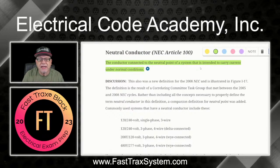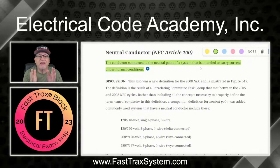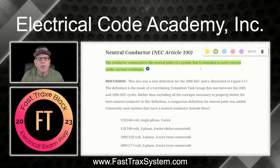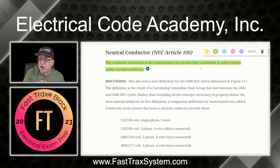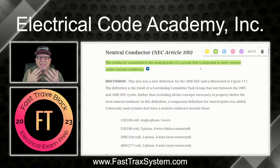Very different from an equipment grounding conductor, which in the service does connect to the same bus as the neutral conductors. But as it leaves your service and goes out, it's important to realize that the equipment grounding conductor is to carry fault current. It's not expected to carry current under normal conditions, only under an abnormal condition, whereas a neutral is going to potentially carry current at any given time. So it's an important distinction.